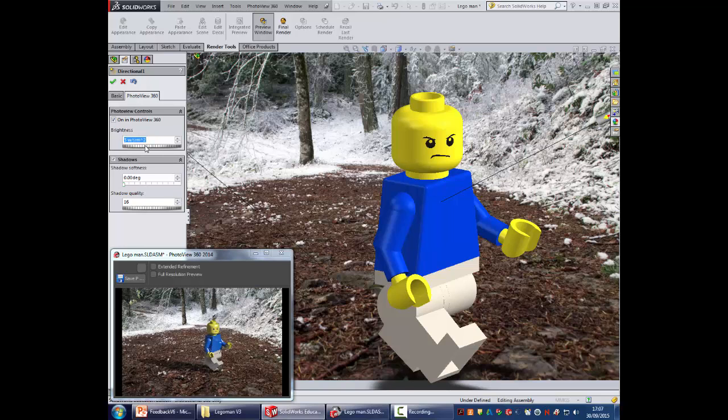Lighting is really important when you're playing with any 3D model, as are the shadows. So you've got options here to play with the shadows. With our current camera view, we've got some small shadows arriving on him here, and I can either play with those in terms of changing the angle of them and the amount of softness, and equally the shadow quality. Both of them will play with the end results, and you'll get a sort of fuzzier, softer shadow should you play with it.